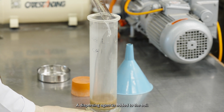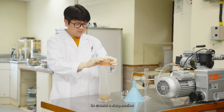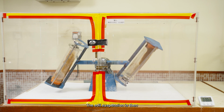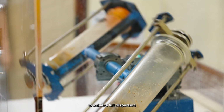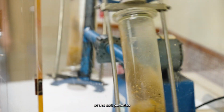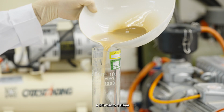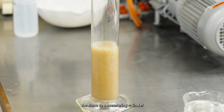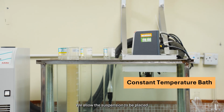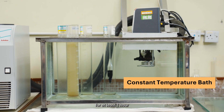A dispersing agent is added to the soil, and these are thoroughly mixed to create a suspension. The soil suspension is then put into a mechanical end-over-end shaker for 4 hours to achieve full dispersion of the soil particles. We then pass the suspension through a 63-micron sieve and transfer the suspension passing the sieve to a measuring cylinder. We allow the suspension to be placed in a constant temperature bath for at least 1 hour.